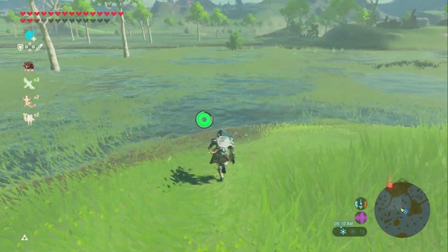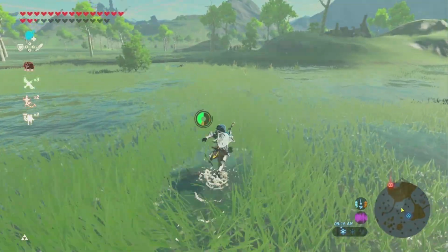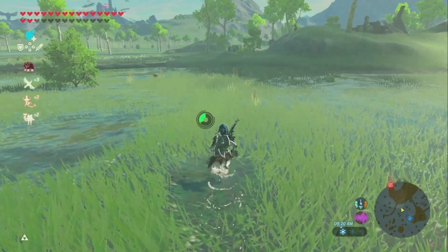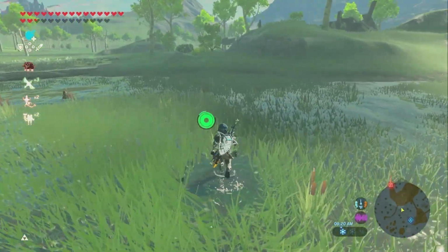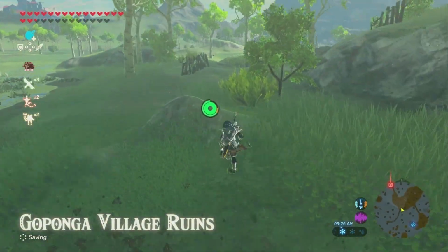In an oil-fired water heater, you may find that the baffle has fallen down into the fire pot or refractory. This can sometimes be seen looking in through the viewing port.